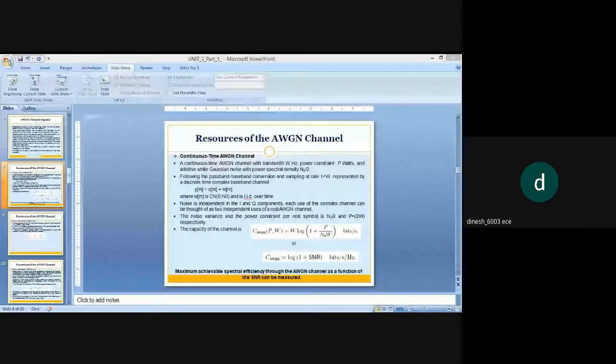Then the fading channel capacity with the channel fade level information at both the transmitter and receiver is achieved or known when the transmitter adapts the power, data rate, and coding scheme to the channel variations.